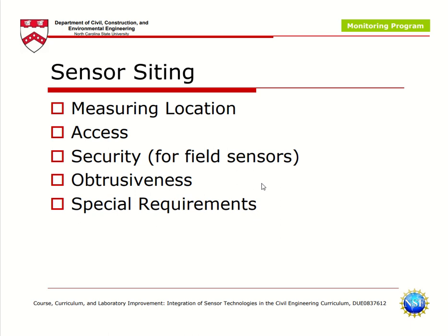So you have to make sure that wherever you have installed your sensor, you must be capable enough to see it, and capable enough to identify the place where you have installed it, right? So it must be accessible. Otherwise, in case of a fault, when you know that this sensor is not working correctly and you want to replace it, what would you do? You will try to remove that sensor and replace that sensor, but it is not accessible.